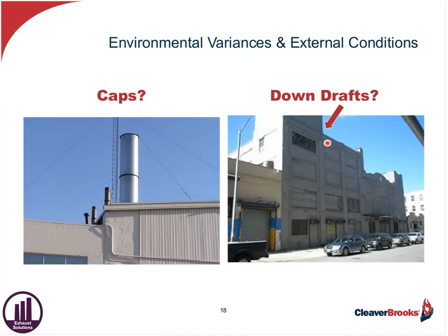Here you see, if we put a stack, here's another problem. This would be an external condition. Let's say that we were coming through this ceiling right here, or this roof right here, with a stack where the arrow is pointing. Notice this column next to it. This could induce a downdraft. So that would have to be taken into consideration. Either we would take that stack up above this column, a couple of stories higher, or we would have to have certainly a cap on top of it.